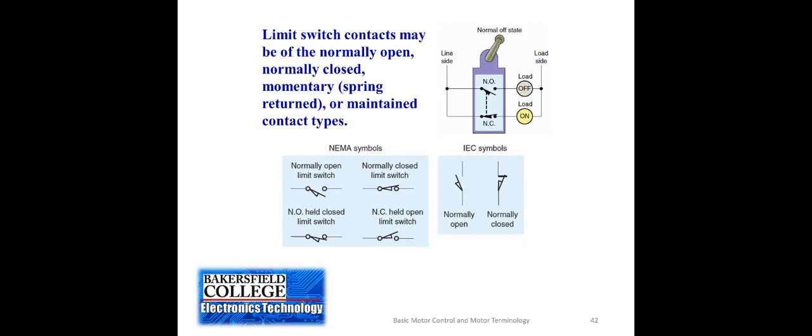Well, if you're using the piece of equipment and either on purpose or accidentally that access door is opened, then the limit switch that's either held closed or held open under normal circumstances changes its condition, and therefore the machine will shut down.